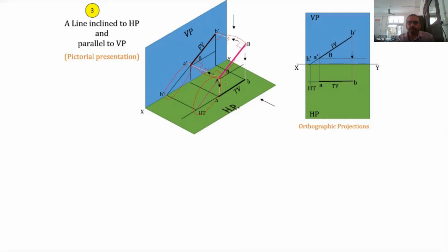But when we consider the top view, this is not actually a rectangle. It is a quadrilateral, a trapezium, in which these two sides are parallel, and this side is not parallel to this line. So that is the difference. In this case, the length of the top view is somewhat lesser. If this angle is theta, which we already know, you can find the length of this distance.